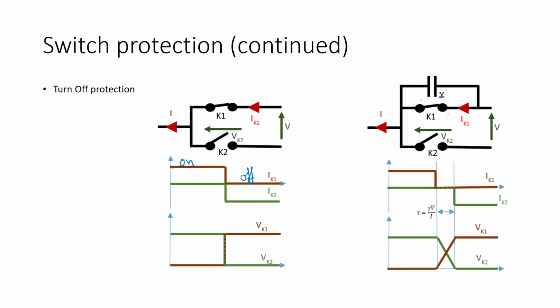How can you do that? You need to have a capacitor in parallel. So voltage does not drop sharply but gradually, like this, or drops gradually or increases gradually. Yeah, so this parallel means parallel for all of these two branches.